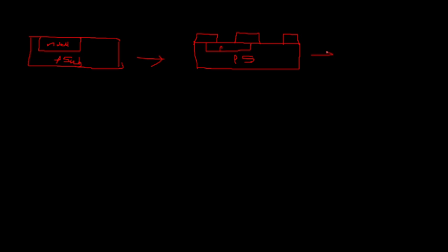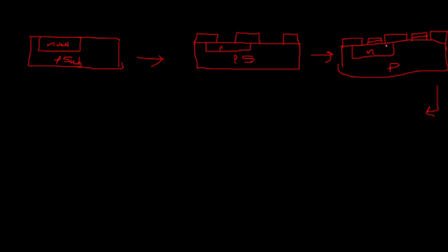Later on a thin oxide and polysilicon layer will be deposited. So this is your P-type substrate into which the N-well is made. This is N-type. Then again a thick SiO2 layer is deposited. After this step, a thin oxide layer and polysilicon will be used for making the gate terminal. Once the source, gate and drain regions are over, you will start diffusing the impurities.